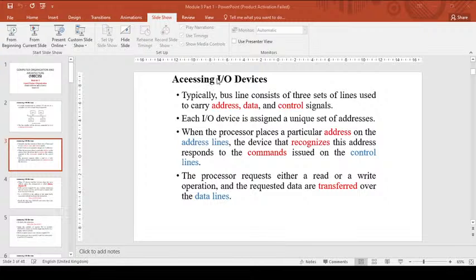That means the data from the register R0 is transferred to the data out register of the display device or the screen, whatever. Data out is a name used in this textbook to indicate a buffer register. All data in, data out are called buffer registers. So data out is a buffer register used in the output device. It can be a display, a printer, or anything. This is how the data is read and displayed using memory mapped IO.